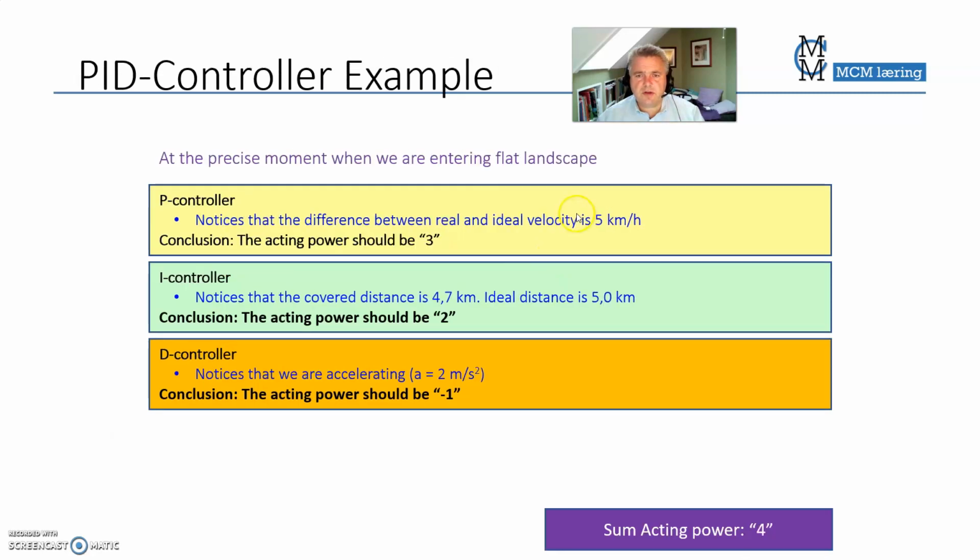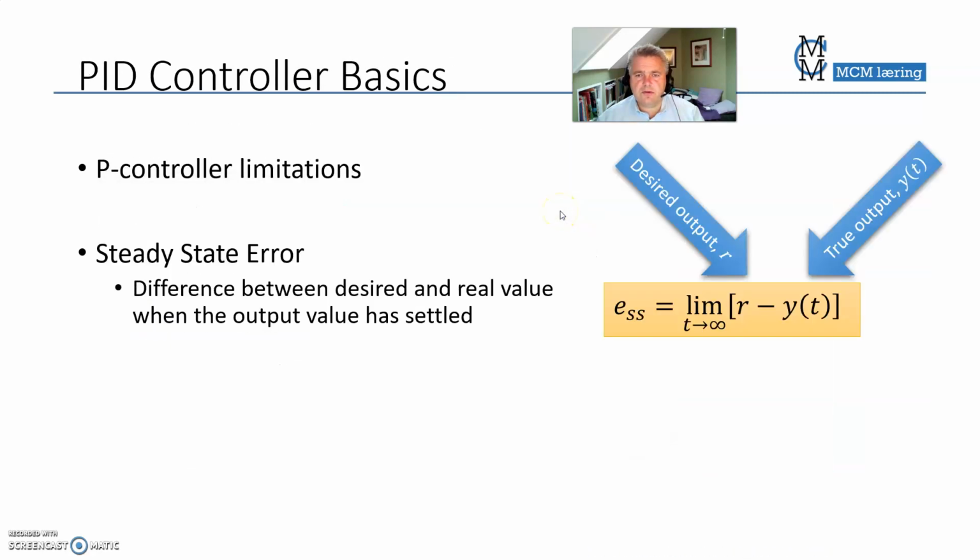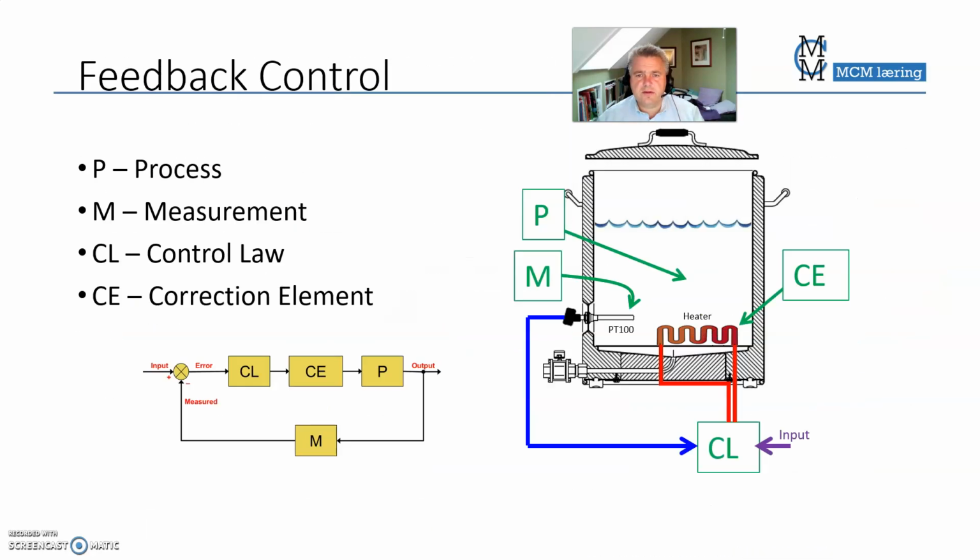So let's go back to the example here, way back to the tank that we had. It's here. If the level of the tank were to rise up here, well, then the P element changes, and we would need to adjust the PID controller again for the new values that go with a full tank.